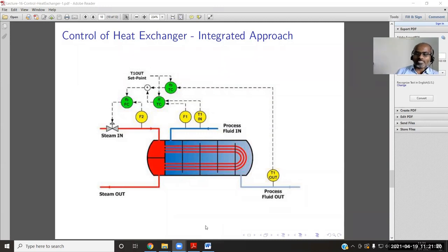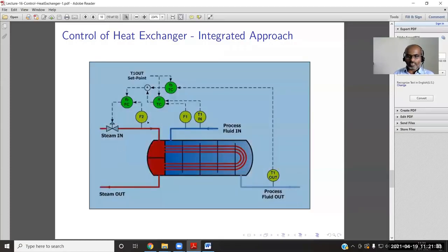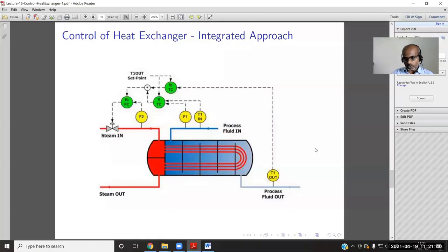These are all happening because sometimes at the last moment we cannot create pressure. Otherwise, putting in inner loops is a kind of delegation. Cascade control, you can consider like delegating the job to your subordinates, and the subordinate has to do the job in a faster way. Then only the delegation will be perfect. Good. Simple. Feedback, feed forward, and cascade.